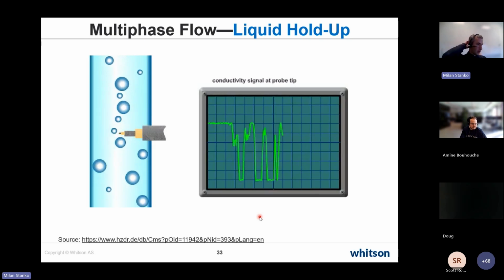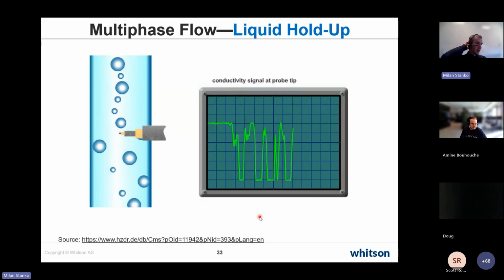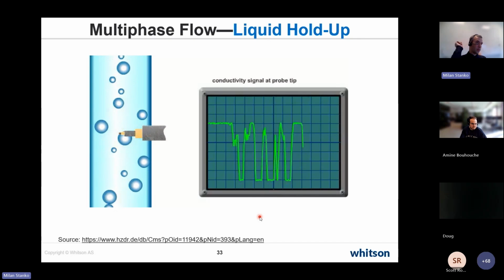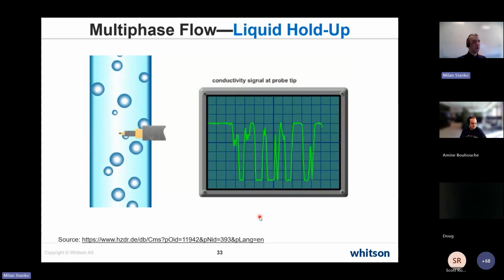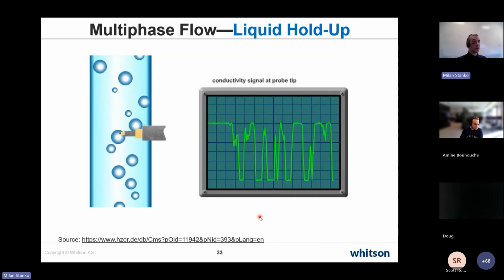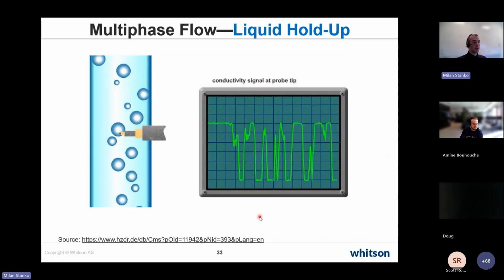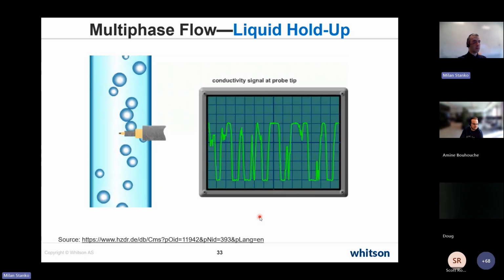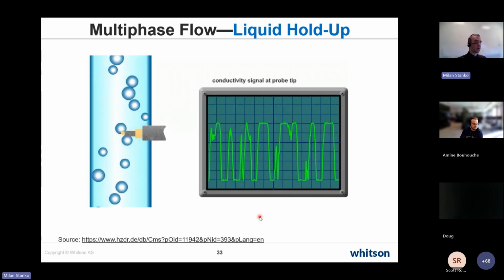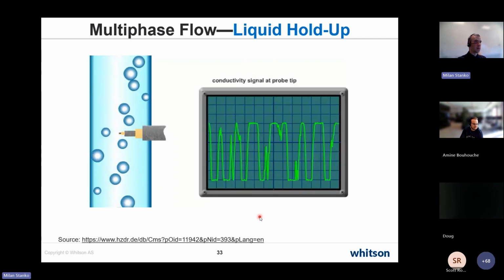Multiphase flow is very complex. It's essentially not steady state. If you pick a point inside the pipe, it will be changing all the time. But by using that, we are predicting average properties in time and space. Actually, we can develop methods that are quite accurate, and for engineering purposes, they are quite acceptable.